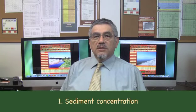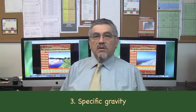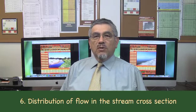Suspended load measurements consist of 1. Sediment concentration, 2. Particle size, 3. Specific gravity, 4. Temperature of water-sediment mixture, 5. Water discharge, and 6. Distribution of flow in the stream cross-section.